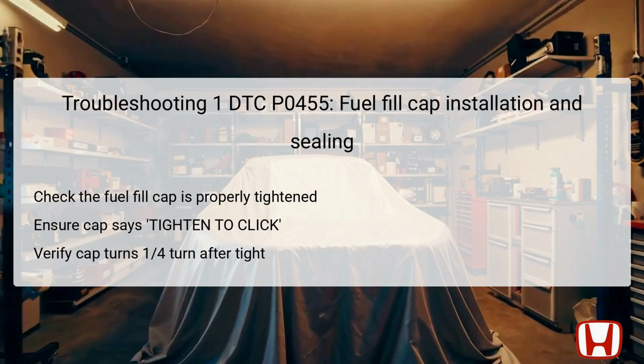The first step in diagnosing a DTC P0455 involves inspecting the fuel fill cap installation. A proper seal requires the cap to be tightened until it clicks, indicating it is securely in place. The cap should also turn approximately a quarter turn after reaching the click point, confirming correct engagement.